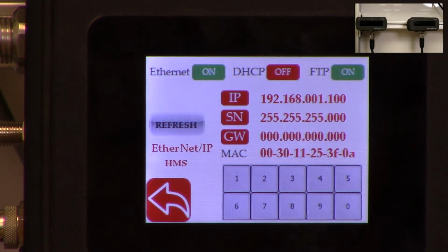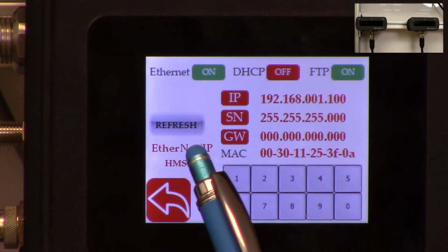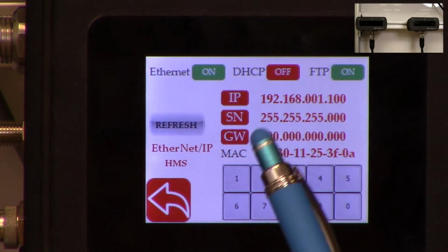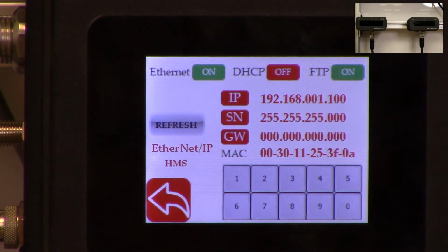If a network device is present, then the controller will actually show the type of industrial network that is here. And this is called Ethernet IP. And in our case, Ethernet IP is the type of industrial network that we are using. Depending upon the firmware version, you might have something here that says what type of module that we have.